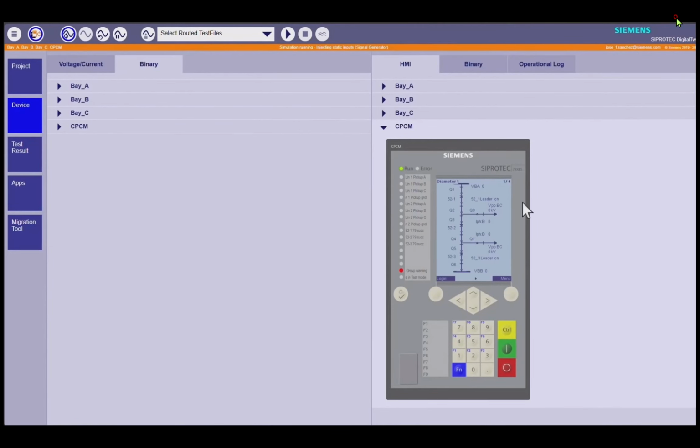Now in digital twin we are going to see how the relay is doing this fault. Then, as I mentioned before, we have some iterations between relay sim test and digital twin. You can see that both circuit breakers related with this line are open. The 52.3, that is the circuit breaker close to the bus bar, closed first. And then the circuit breaker 2, 52.2, is closed later.